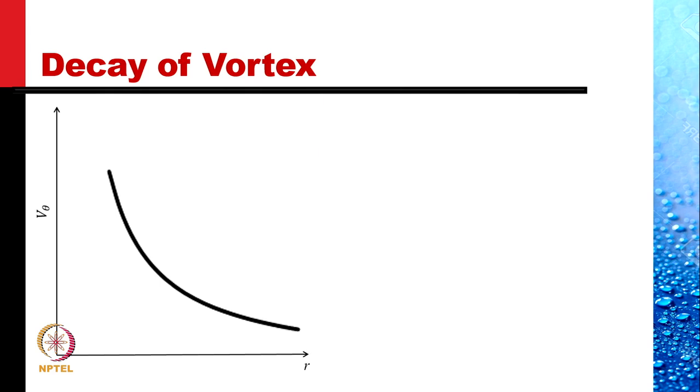This velocity profile, V theta versus R, because of the large gradient near the center, the flow near the center is viscous, and since it is viscous, it's more like a forced vortex where the velocity varies directly with R, increases with R. And after achieving a maxima, the free vortex takes over and the flow velocity varies like this.